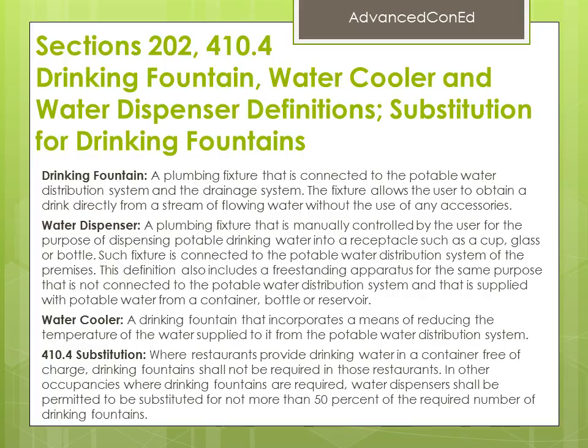410.4. Substitution: where restaurants provide drinking water in a container free of charge, drinking fountains shall not be required in those restaurants. In other occupancies where drinking fountains are required, water dispensers shall be permitted to be substituted for not more than 50% of the required number of drinking fountains.